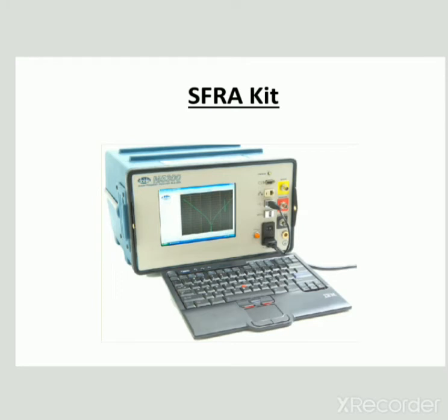Next, images of the SFRA kit. SFRA means, as already seen, sweep frequency response analysis. This analysis is one of the most powerful diagnostic tools for assessing mechanical damage to a transformer winding. Analysis of the results, which are in the form of frequency response traces, can, however, be daunting to new users. So this is all regarding the SFRA kit.